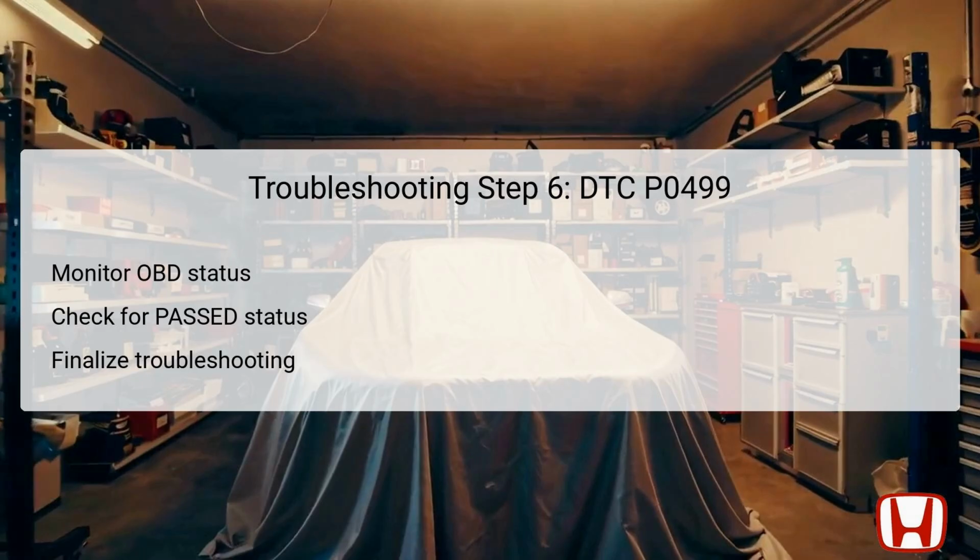However, if you substituted an ECM or PCM and the trouble code remains clear, you will then need to change back to the original unit. If any pending or confirmed DTCs are present from earlier checks, you will redirect efforts to their respective troubleshoot guidelines. This systematic approach reinforces consistent and thorough investigations of the vehicle's electronic and emission control systems.